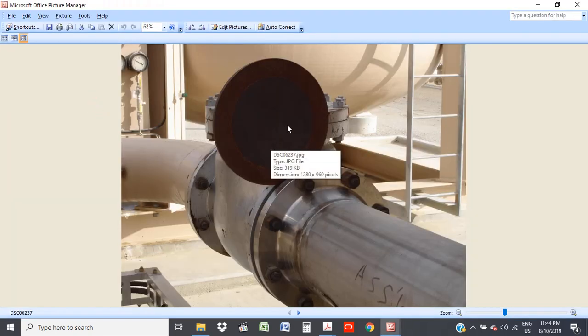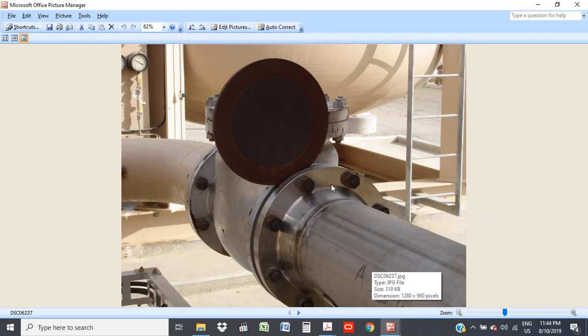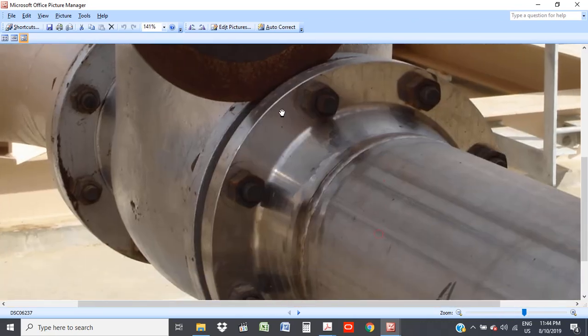So this is it. On this side there is a ring with a hole in it, so it allows flow to go across. The hole is the same bore as the pipe diameter. It's like a flange. It's cut to fit between two pipe flanges. Can you see these two pipe flanges? So it fits in between those, and is usually sandwiched between two gaskets.